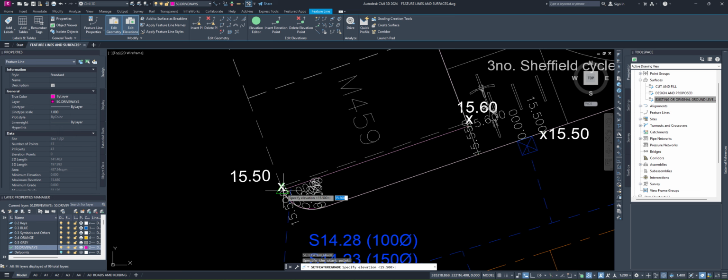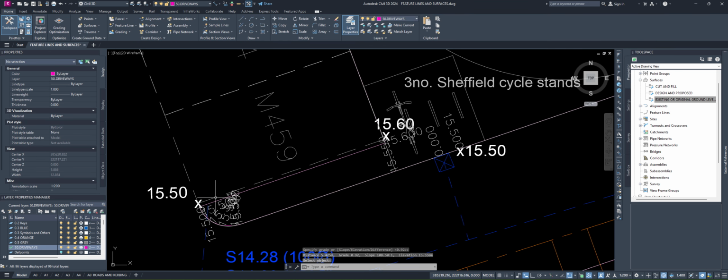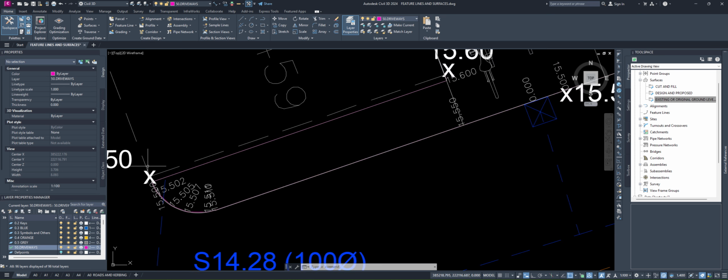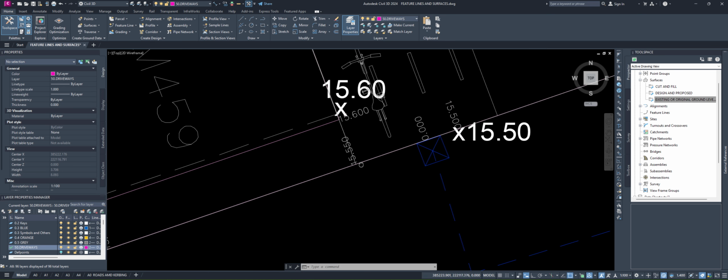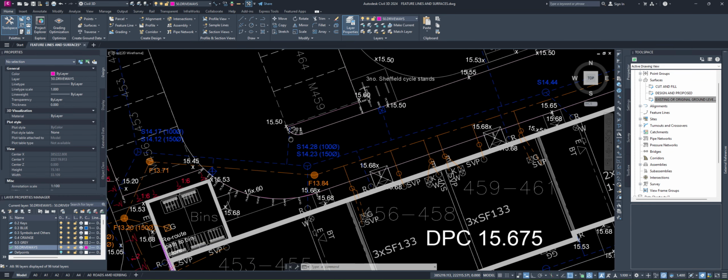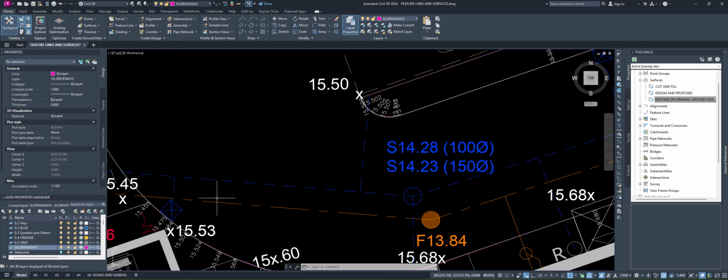Okay, I'm gonna start from that point where I'm 15.500, going to the next point, which is 15.550. Gonna press enter. You can see how my levels are gonna change along. Let's make our level slightly smaller by decreasing the scale. Now this way I can actually see what is happening over here. Okay, we can see we are falling back towards this end, from this end, sorry.